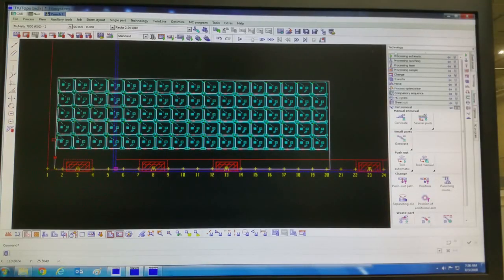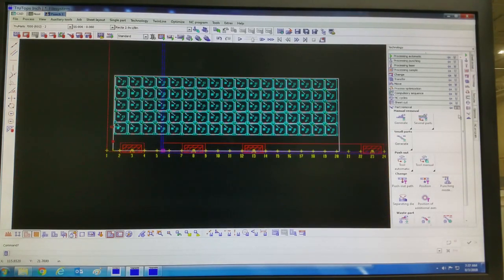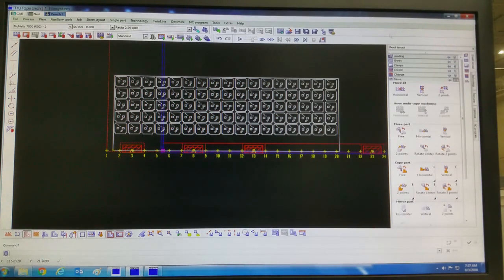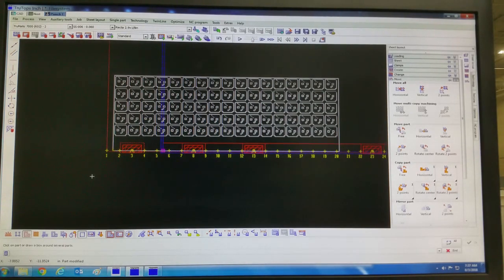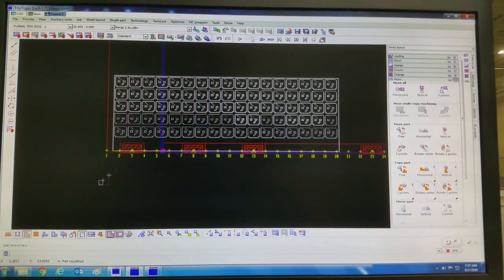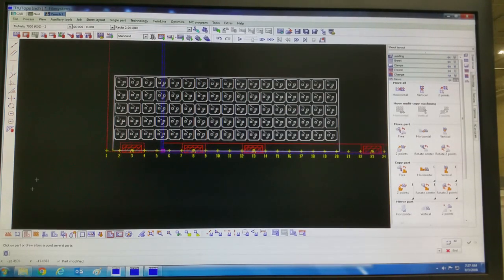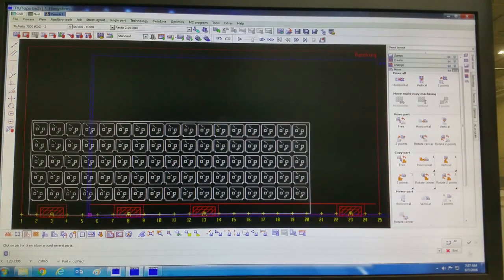But never mind, that's okay. At least I can keep bigger space between the parts. So I go to sheet layout, I go to move, and I want to move part vertical, let's say 0.3. And like that, I divided the space between the parts. Yeah, so that's pretty nice. I have no problem with that.